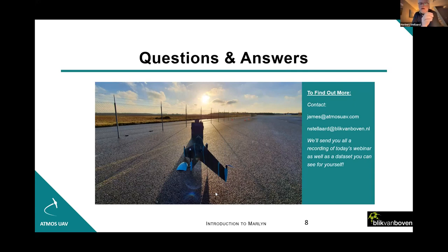For high accuracy, if you want to have it in an absolute way, then you need to have a known point. So the base station has to be positioned on a known point. If it's based on relative accuracy, then that's not necessary, because then the accuracy you need is only relative to the known object. So to summarize, for absolute accuracy, yes, you need to know the position of the base station. For relative accuracy, no, that's not necessary.